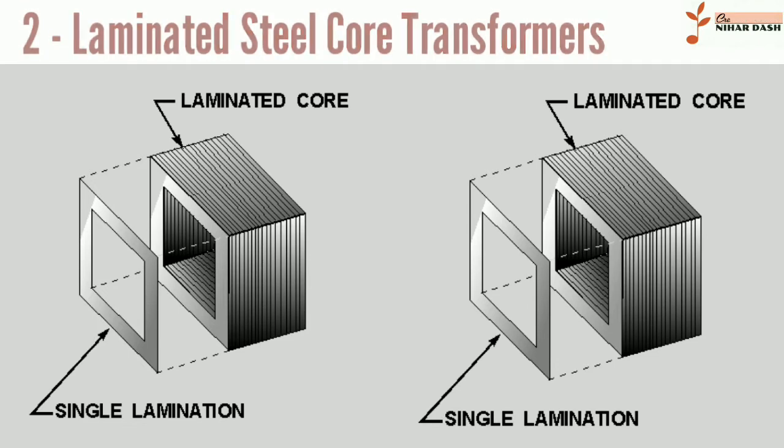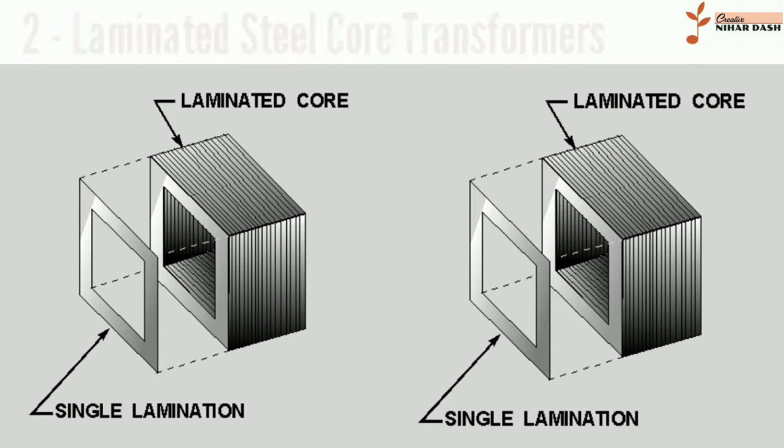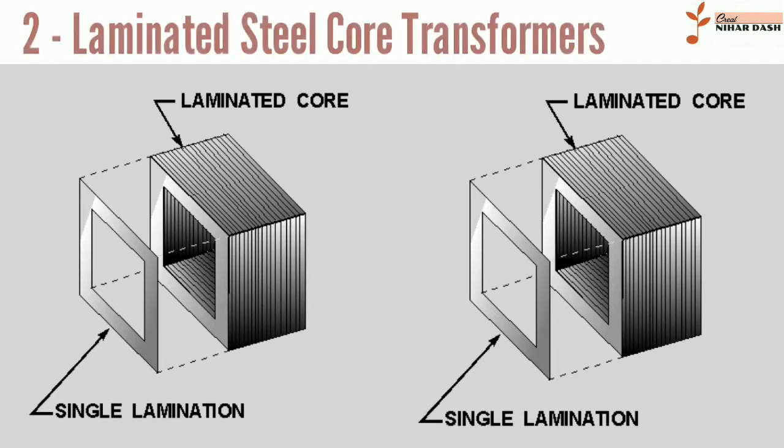Distribution transformers can achieve low no-load losses by using cores made with low-loss, high-permeability silicon steel or amorphous, non-crystalline metal alloy. The higher initial cost of the core material is offset over the life of the transformer by its lower losses at light load.